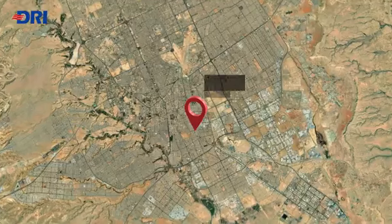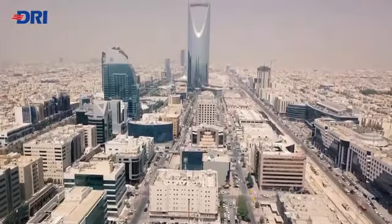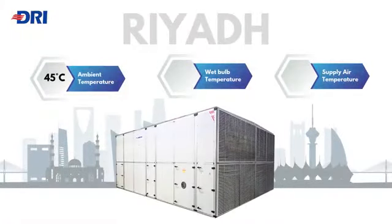In a hot and dry climate like Riyadh, where summer temperatures can soar above 45 degrees Celsius, with a wet bulb temperature of around 18 to 20 degrees Celsius, traditional air conditioning consumes enormous energy to maintain comfort. However, an IDEC system can reduce the supply air temperature to nearly 15 to 17 degrees Celsius, that is 59 degrees Fahrenheit, well below the wet bulb temperature without relying on high-power refrigeration, significantly cutting energy costs.